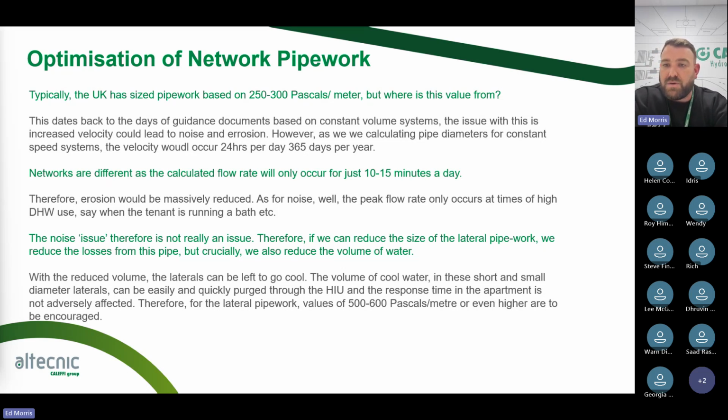It's all about surface area. It's all about, you know, transmission of heat. The better heat networks are ones that transfer the most heat. So if we can draw that out by using larger surfaces like bigger rads, underfloor heating, utilizing those bigger areas to take the heat off, the more efficient the network will be because we're increasing that delta and we're taking more energy from the system. But as I say, we'll look at those as we go a little bit further into the presentation.